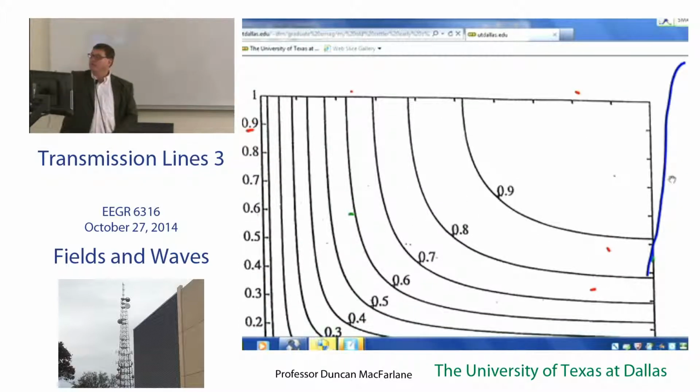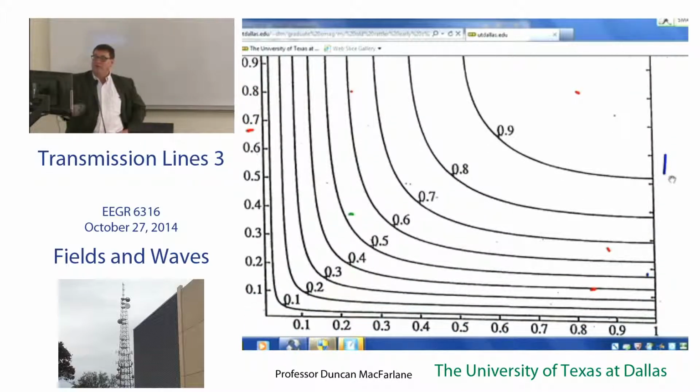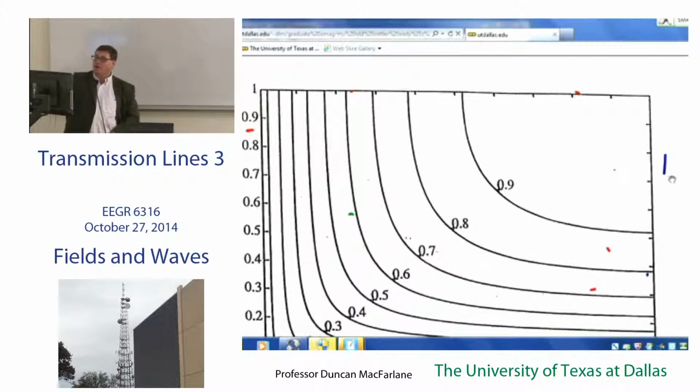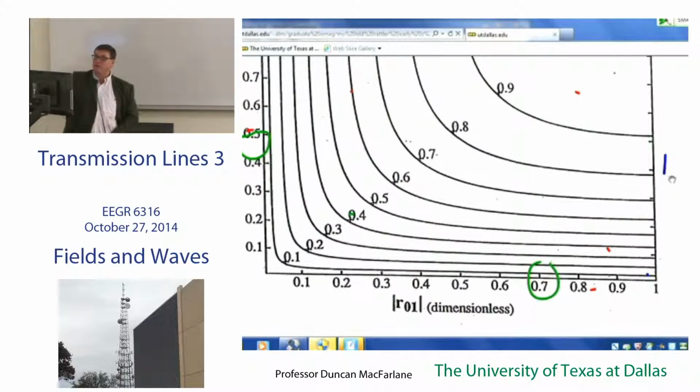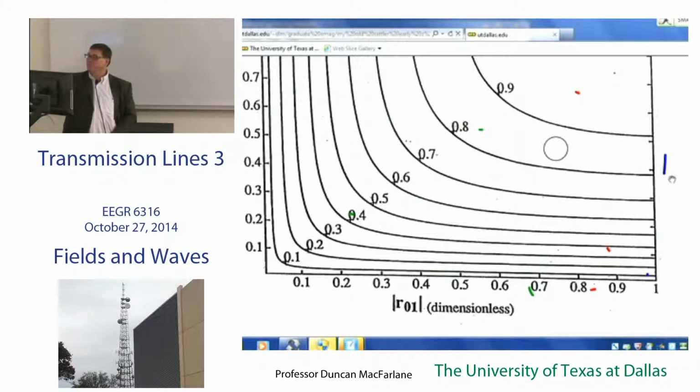Here's that resonance condition plotted as a contour plot. So I have R2,3 in the middle. I have R at one end, I have R at the other end, and here's my R in the middle. So if I pick a particular R on the output, take another R on the input, I read across, and I find out what the third reflection coefficient should be for the middle. And that's how I know that I've satisfied both of those poles on top of each other. Okay?